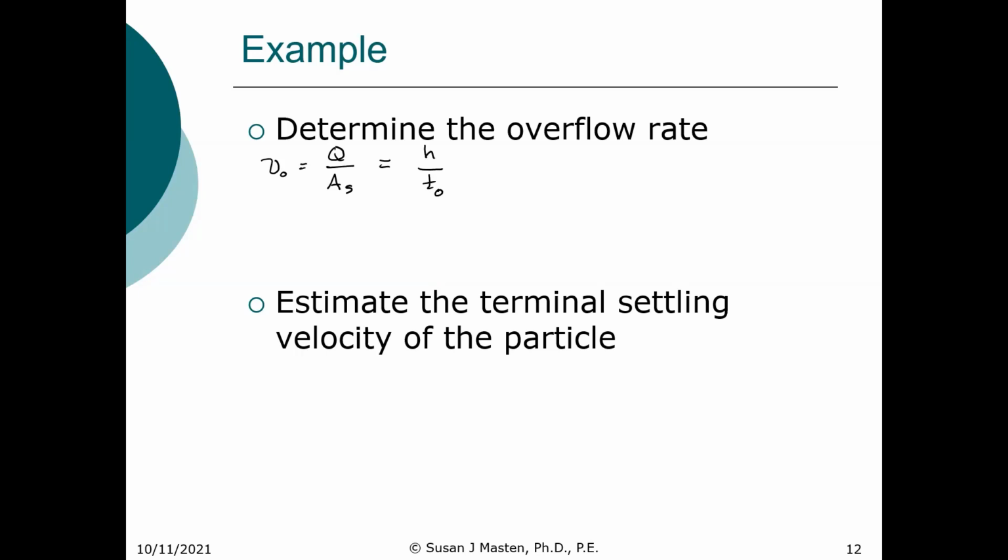And in the sedimentation lecture, I go over the derivation of those equations. So that is equal to the 1.0 meter depth divided by the detention time, which is given as 60 seconds. So that is 0.0167 meters per second.